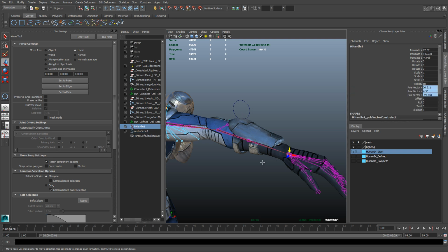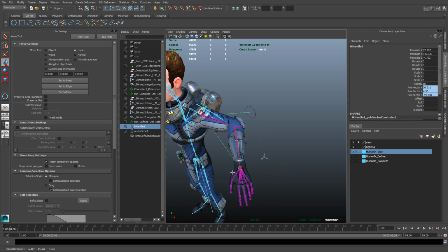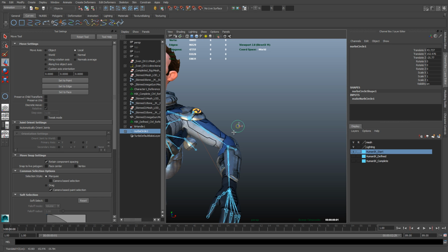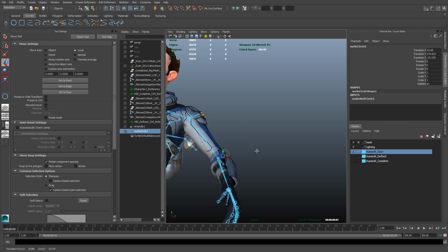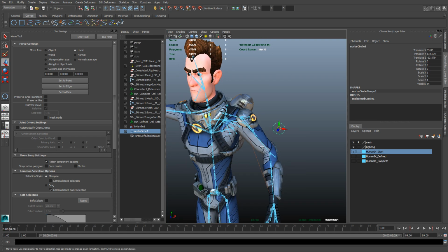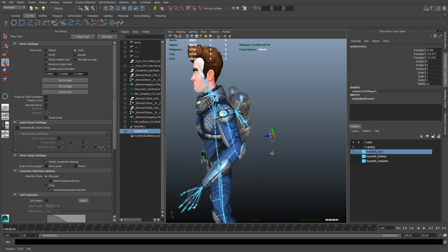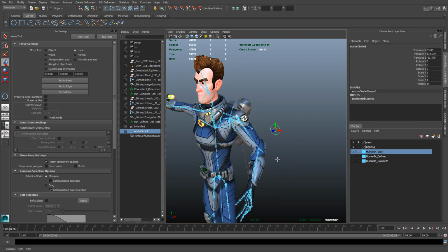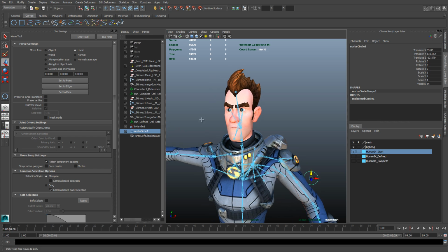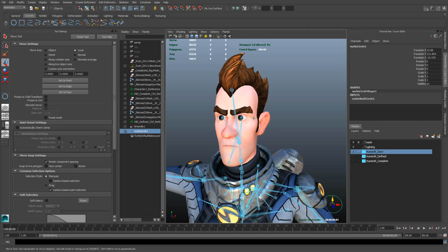So now, if I animate my arm using IK, so I'll just bring it down to here, I can also control the position of the elbow, so I can twist it just like that. Constraints are very handy, and using curves as control objects is also a very important part of creating a character rig. So let's look at one more example of using curves and constraints. In this case, we're going to use the look at constraint and some control curves for the eyes so we can control where our character is looking, at least with his eyes.